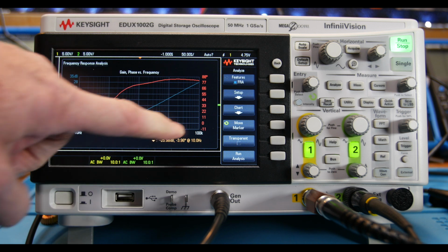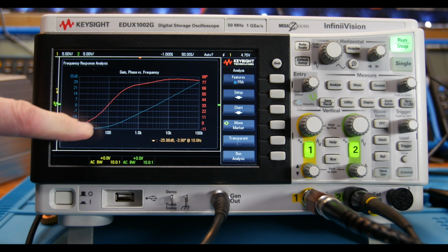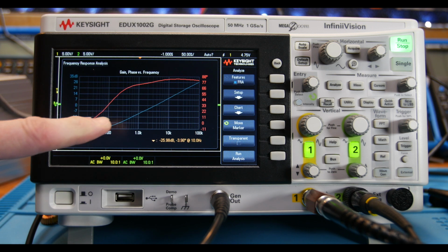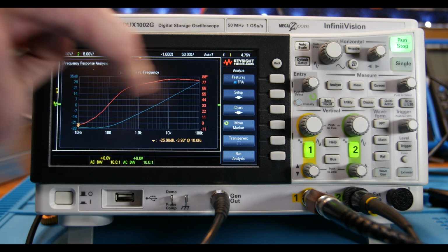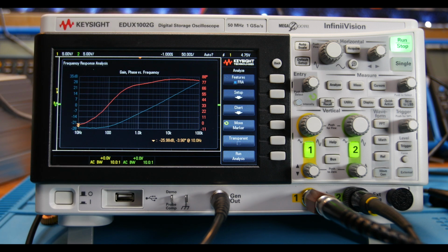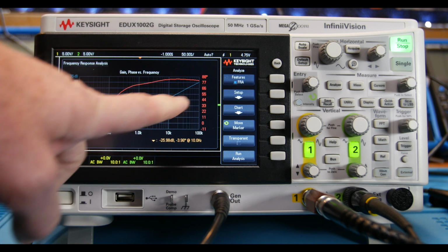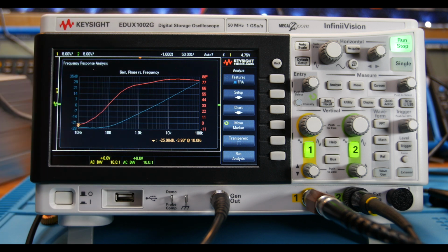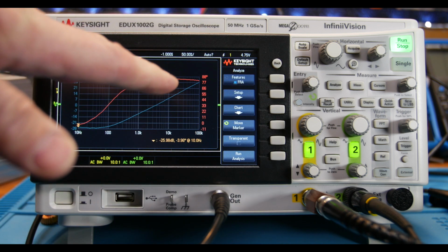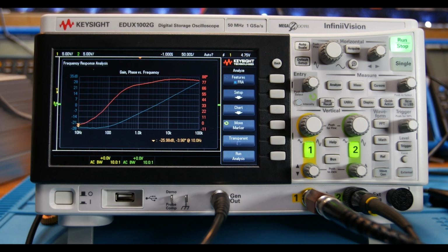The phase starts around 0 because it looks more like a resistor, and then it starts to look like an inductor, so it comes up to what should be about 90 degrees, and it looks like it goes up to about 88. So that's looking pretty good. Isn't that cool? If you don't have an inductance meter, you can use your oscilloscope to read the inductance. You can calculate the DC resistance and the inductance from this. Now if we went to higher frequencies, we might be able to see what kind of capacitance it might have, but we just went to 100K in this example.